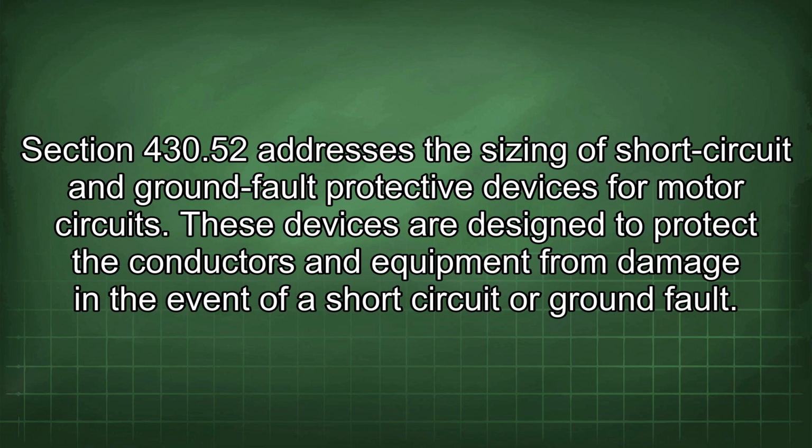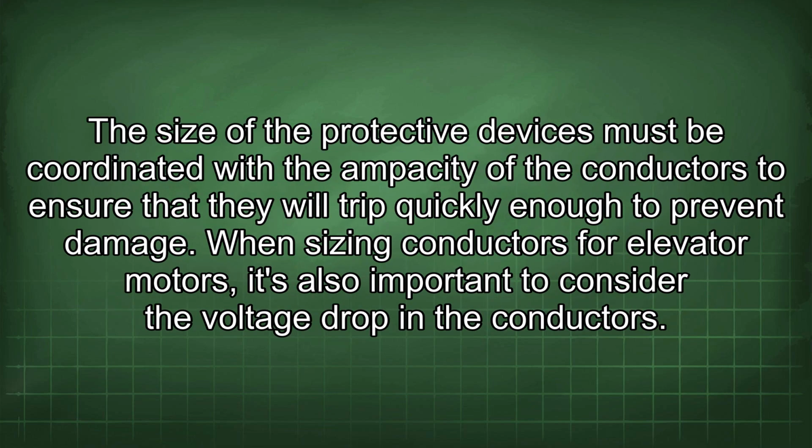These devices are designed to protect the conductors and equipment from damage in the event of a short circuit or ground fault. The size of the protective devices must be coordinated with the ampacity of the conductors to ensure that they will trip quickly enough to prevent damage.